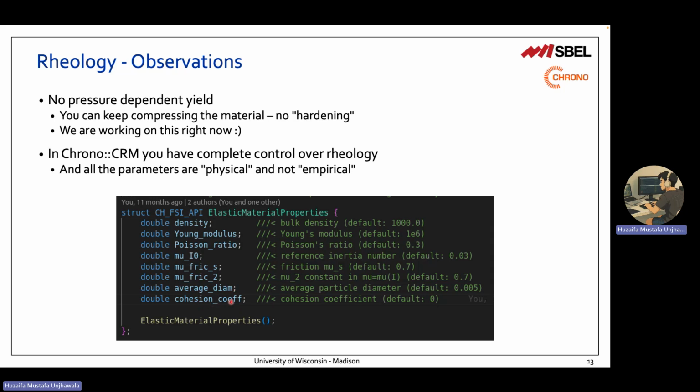And we also have this additional parameter called cohesion. This helps model that sometimes the soil is not fully dry, right? If you put wet soil in an hourglass, you'll see that even when the particles are falling, they're not separate particles, they are sticking together. This helps model that, although it's not exactly modeling that; an accurate model for that is in progress. But if you want to quickly have something where the particles are not fully disjoint but kind of stuck together, then you can increase the cohesion and make the terrain more rigid and less fluffy.